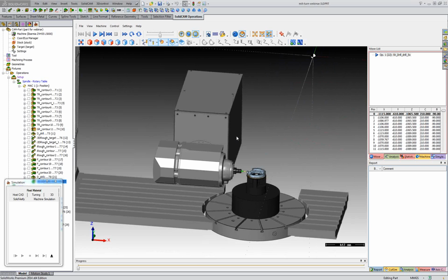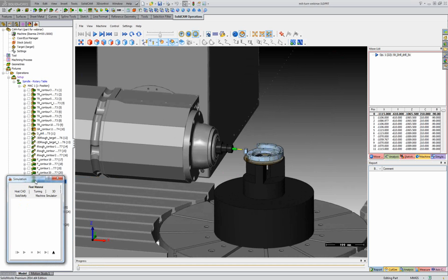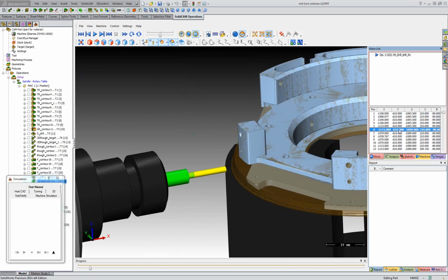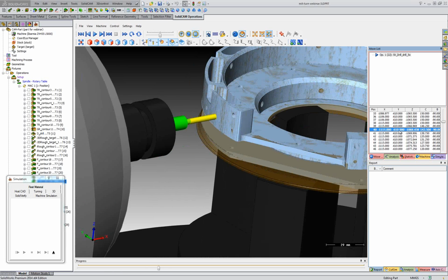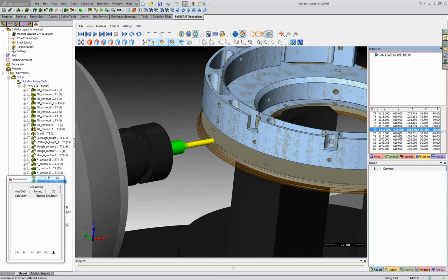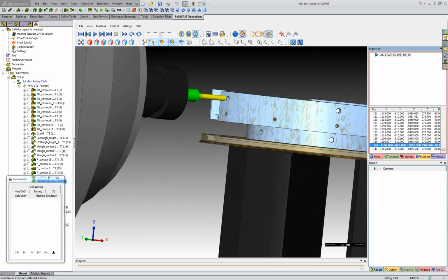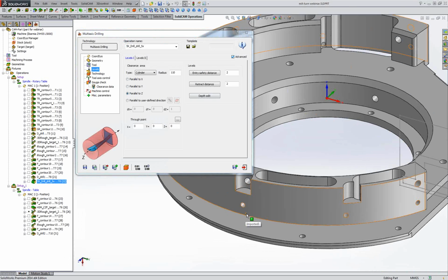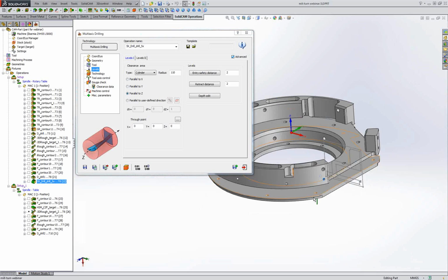As we see, I told you I always prefer to work on this side because of lack of space on the right side. So in our operation we can always select the first angle pair or second angle pair. Start drilling inside, also rotating the part, all this in one operation. So my part is finished on this side. Of course, we didn't drill those holes. We can add a new operation and drill them.